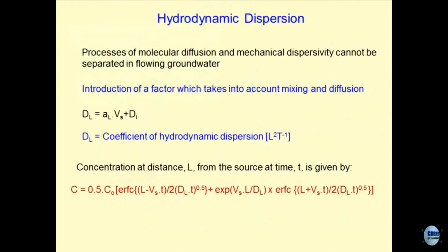The fourth process through which the contaminants might migrate in the porous media is hydrodynamic dispersion. So, hydrodynamic dispersion is a process where some mechanical activity is required to trigger or to accelerate the molecular diffusion. A good example would be the potassium permanganate which I added to the water column in the glass. If I let it happen on its own, it will take a lot of time.